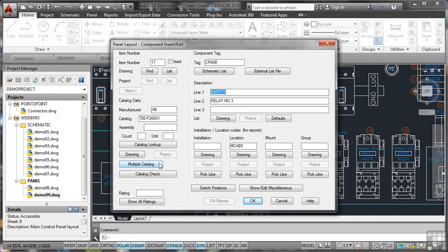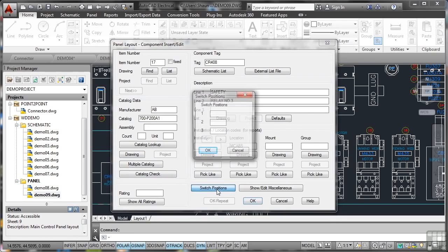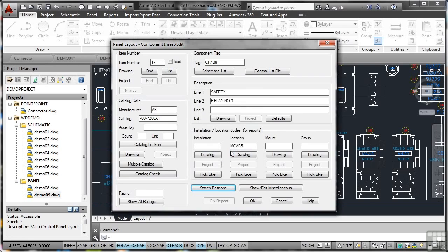And I can link it with a drawing or a block or switch positions. I can change everything there. So go to switch positions there. There we go, 1, 2, and 3. It's got 3 switches. Where are those positions? On, off, and so on. So there's some clever information there that can be utilised to your advantage. It saves you having to draw all of this by hand and manually do electrical on AutoCAD. That's the whole idea of AutoCAD Electrical. It's got the AutoCAD in there, but it's also got the electrical tools to allow you to work with AutoCAD and make you a lot more productive.